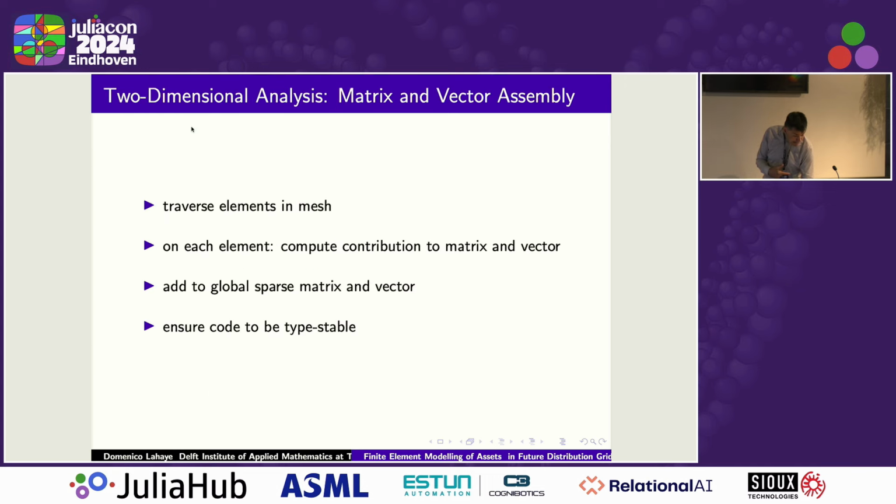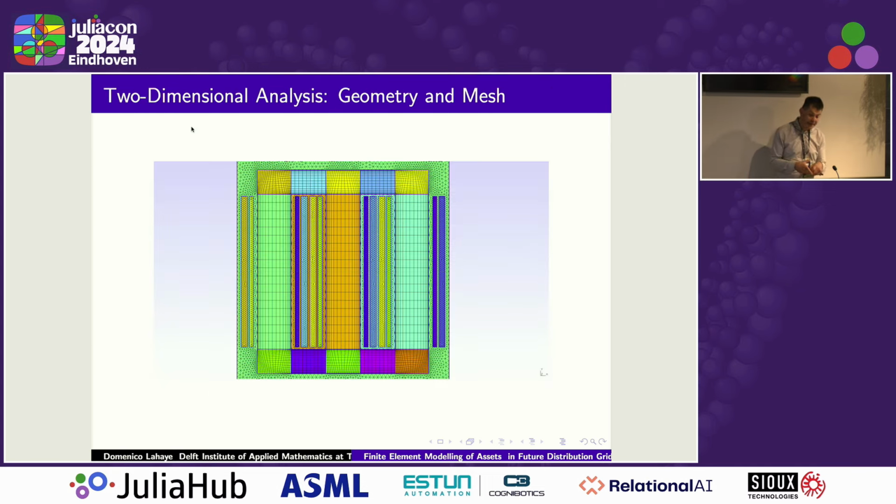Therefore, this mesh was not generated by coincidence. We know a priori from analytical computations where the flux will concentrate, for instance at the sides of the core limb due to skin effects, and therefore do a local mesh refinement there a priori. So this is already taken into account in the simulations.